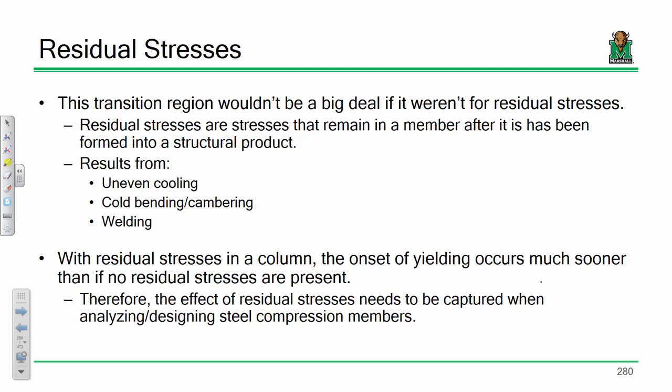But then what happens to the I-beam or to the W shape? It cools down, right? You've got this really hot shape and it cools down. Well, the problem with that is this actually doesn't cool down at the same rate. Think about thermo. Oh God, I'm bringing up thermo to a bunch of civil engineers. Wouldn't it make sense though, just from basic common sense, that if I heated this thing up to like 2,000 degrees and just set it down, the tips right here would cool first, and then maybe this would cool? What's the last part that's going to cool? Where they come together, right? This flange web junction right here.